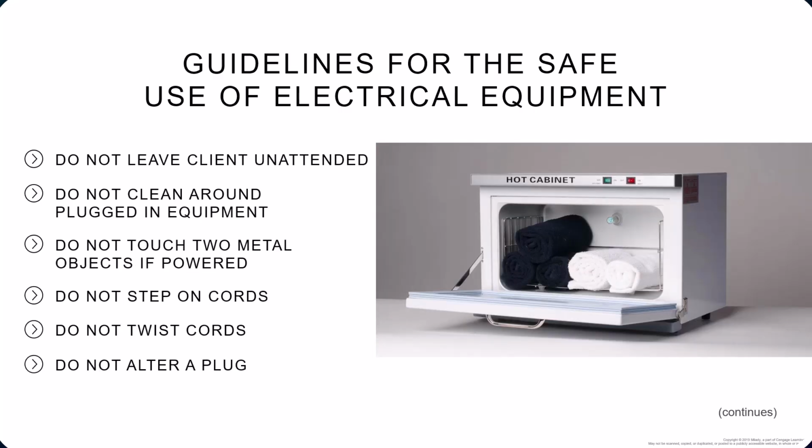Avoid contact, for both you and your client, with water and metal surfaces when using electricity, and do not handle electrical equipment with wet hands or while standing on a wet floor. Keep electrical cords off the floor and away from everyone's feet because getting tangled in a cord could cause you or your client to trip. Do not leave your client unattended while the client is connected to an electrical device.